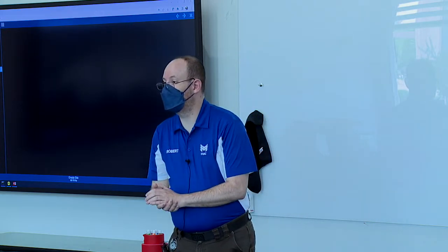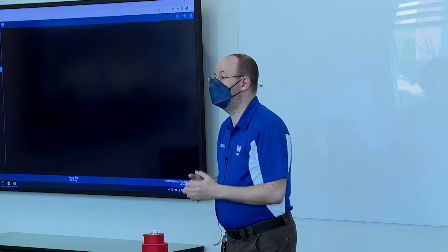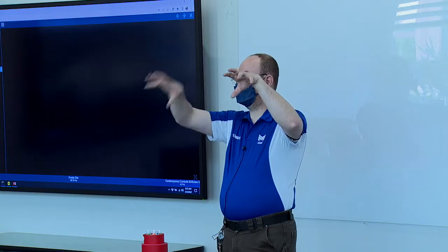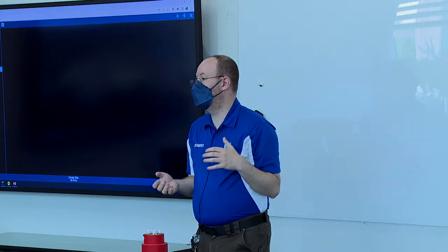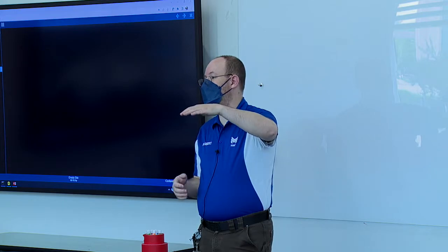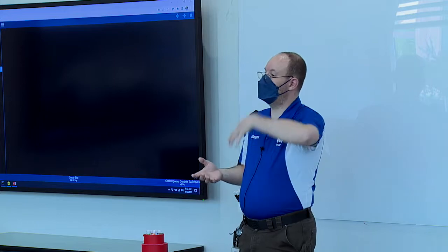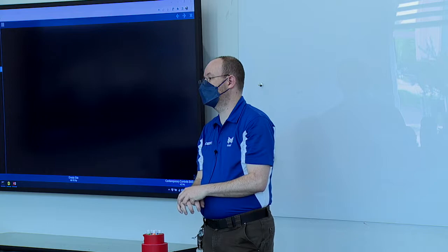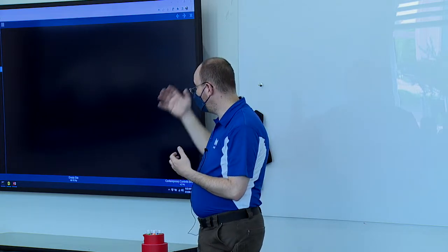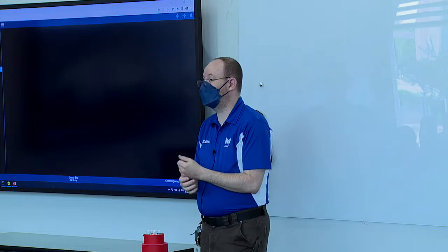Okay? But other things that would be useful might be software-based alarms. We need to do a little bit of math and have a placeholder to build an alarm off of. Or maybe we want to look at the error between our discharge air temperature and its set point, and we want to log that error. So we've got to do some math, and then we've got to stick it in a point before we can log that data. Those are the kind of things that we very frequently use virtual points for.